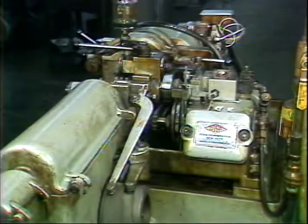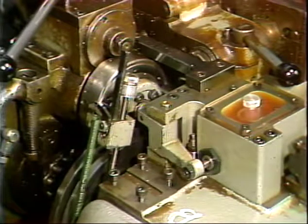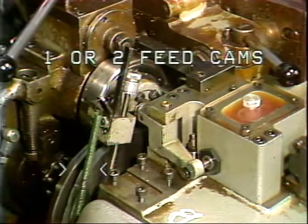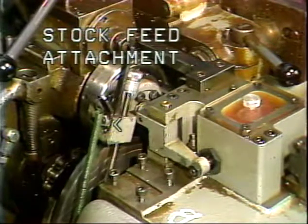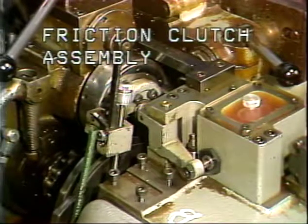The stock feed system controls the movement of stock through the machine. Timing of the stock feeding is coordinated with other operations of the machine to assure accurate stock feeding. The movement of the stock feed attachment is caused by the rises and dwells of the stock feed cam. The stock feed attachment transfers the stock feed action to the friction clutch assembly.